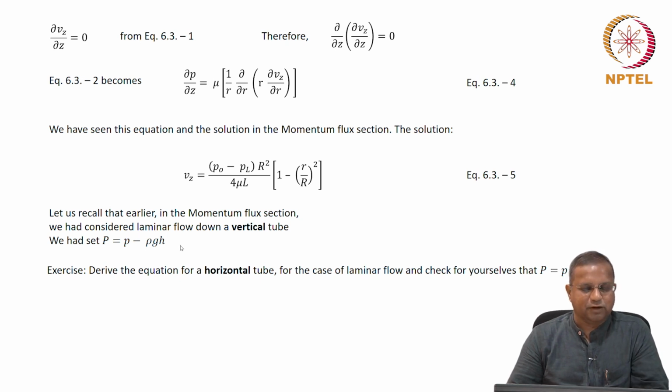It simplified the solution. What I would like you to do is pause the video here, derive the equation for a horizontal tube for the case of laminar flow, and you need to check what happens there. Check whether this capital P reduces down to just the pressure alone.